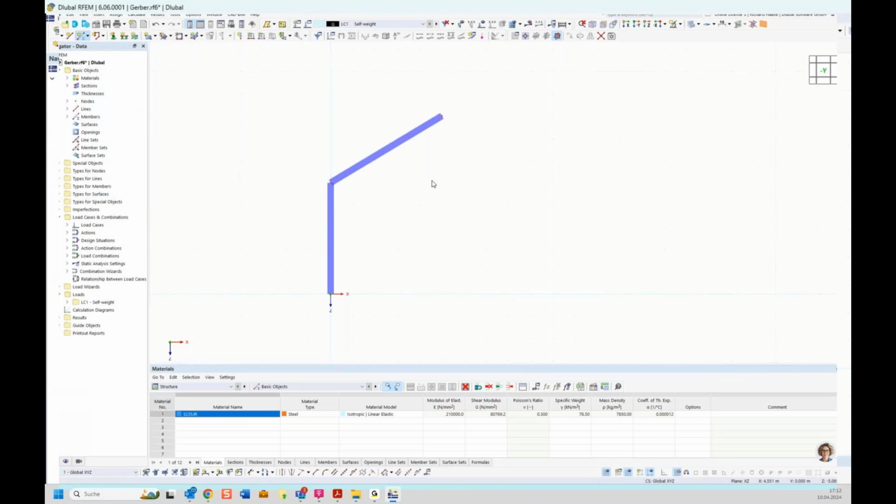And now, okay, our frame is symmetric. So you have the option, okay, you draw 2 other beams, but I will show you an option. Here it's fast, but when you have a big hall and all is symmetric, you only need to model the one half and the other you can make here. You can mirror the objects, and now I will show you how it functions.